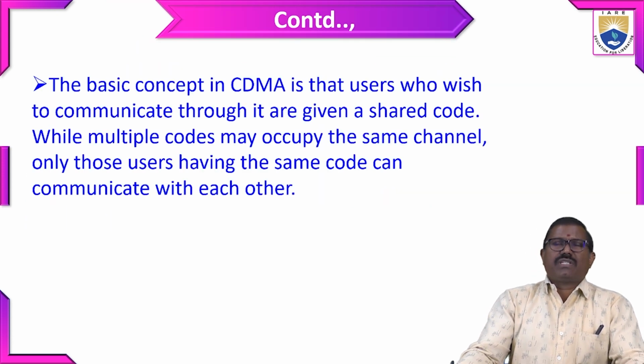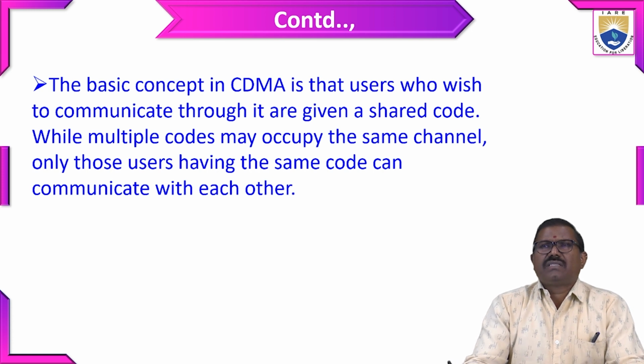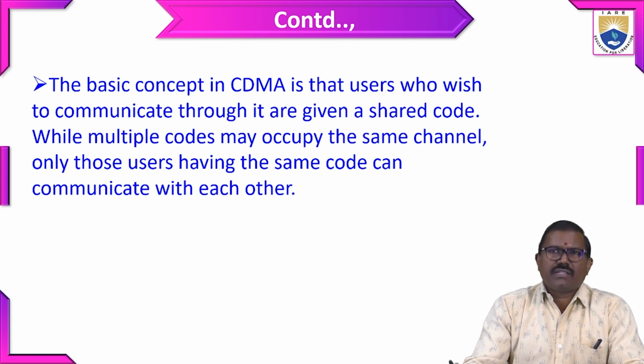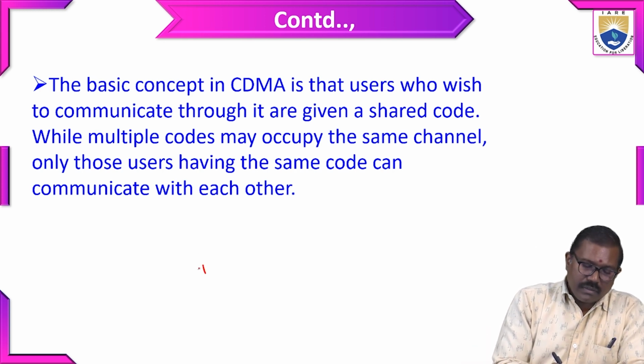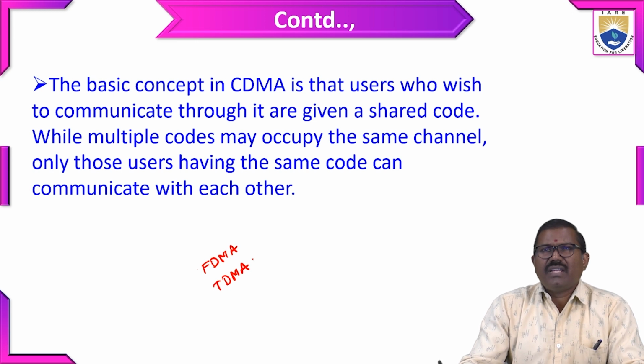So the basic concept in CDMA is that users who wish to communicate through it are given a shared code. While multiple codes may occupy the same channel, only those users having the same code can communicate with each other. So already we know this CDMA is nothing but a multiple access technique. Previously we had FDMA, frequency division multiple access, then TDMA, time division multiple access, and finally CDMA.